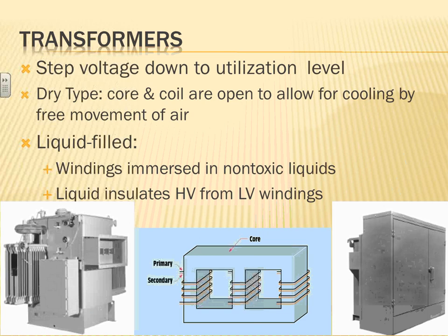Just a quick review. All of you are designers, so you went to school, and you know what transformers are. Transformers, in our world, step down the voltage to be utilized. I don't know if you use transformers to step up the voltage for transmission or distribution. I don't think you do a whole lot of stepping it up. Most of what you do is step down the voltage so you can utilize it. So bring 13.8 to the building, we step it down to 4160, we can run some chillers at 4160, or we take 13.8 at one level, we step it down to 480/277 to run our lights and chillers and so forth. So that's what we call a step down to that utilization level.